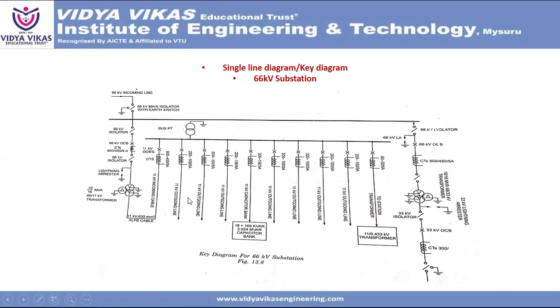From the 11 kV bus bar, they are going to give the outgoing lines: outgoing 1, outgoing 2, outgoing line 3, and then capacitor bank, outgoing 4, 5, 6, 7, and then two station transformers, 11/0.433 kV transformer, and then another connection from the 66 kV isolator only. Here you can observe this is 11 kV, this is 66 kV only.